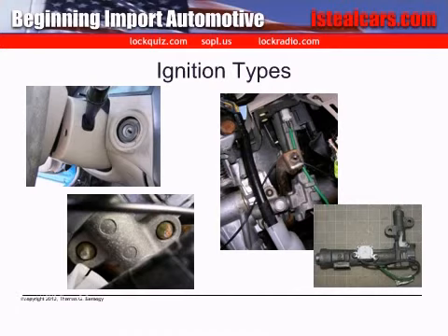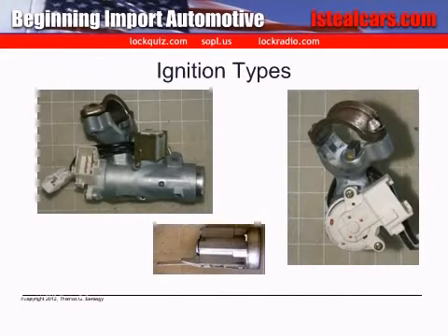On many cars, the ignition appears to be part of the dash. However, once the left or driver's side hush panel is lowered, it is easy to see that the ignition assembly is actually mounted to the column and also fastened using breakaway bolts.